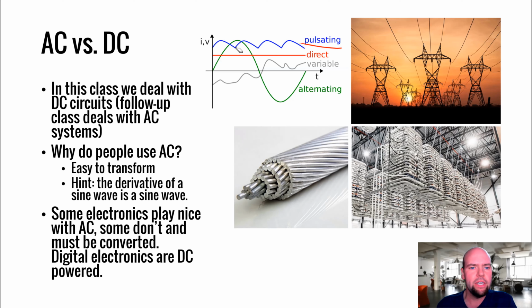I think what people are referring to is, in the early days of power delivery systems, your options were essentially AC, which was a higher voltage AC, and DC, which was a lower voltage DC. And I think that perception of DC doesn't travel as far comes from historically when people were actually selling DC power as a distributed power technology. They were only using 100 or 120 volt DC. And it is true, if you're limited to 100 volts, that's going to take a lot of current to transfer a lot of power.